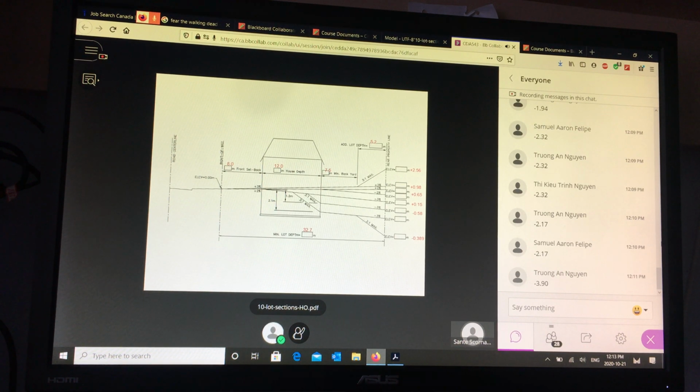So again, these are different thresholds. Now this one in the middle, the one I skipped, is just where the back split starts. So generally speaking, I usually ignore this, but it's worth noting. Usually if the front and the back have a vertical difference of about 4 feet or 1.2 meters, then you'll end up with a back split or a walkout. So this is a simple split. Anything between here and here is going to be a simple split. As soon as you get below that threshold, you're getting into back split territory, this area here.